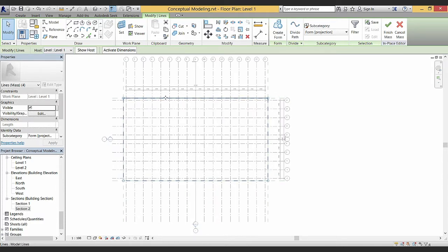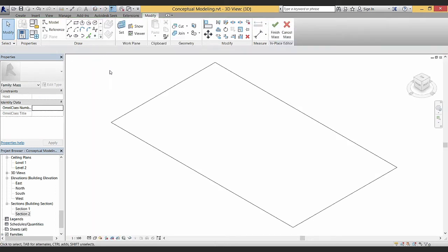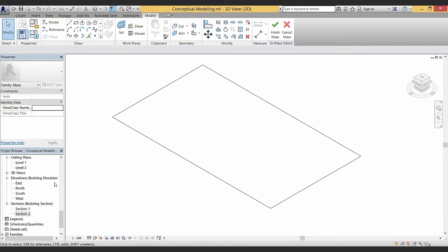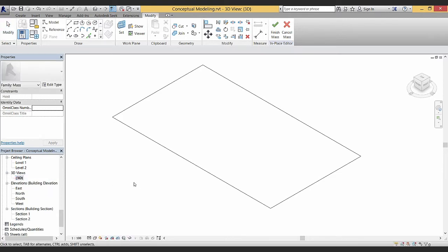And now I think it's time to open a 3D view to see this shape better. So you can use the default 3D view command up here in the quick access toolbar. Just click default 3D view. You'll enter a 3D view. Actually, a new view is created in your project browser. You can see it here under 3D views. 3D. It's bold now, so it's active.